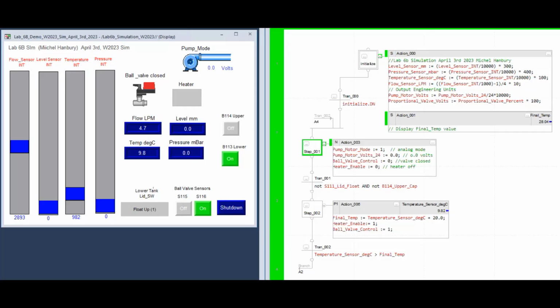This video demonstration will go through the differences between stored actions, non-stored actions, and a P1 action. A stored action executes even when not on the step. One of the ways that you'll notice it's a stored action is that there will be this green box just to the left of the stored action, which means that it's being executed. Whereas a non-stored action, like in this box here, is being executed while it's on that step.